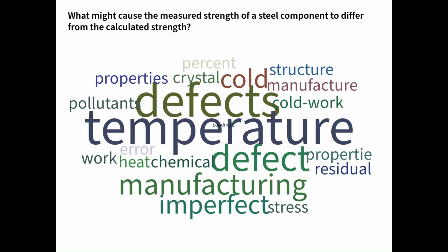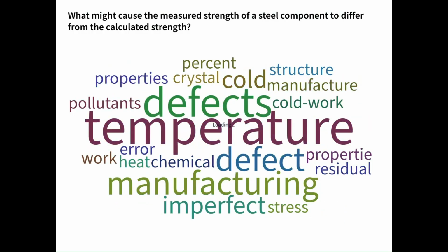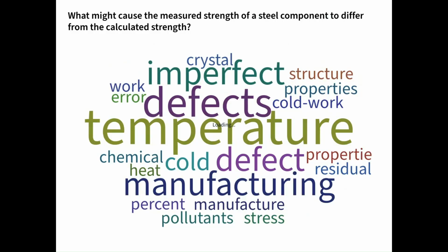You say, I'm going to roll a half-inch plate. You ask them to roll you a plate to exactly 12.7 millimeters, and they're going to do it. And then you take a pair of calipers, and it's actually 12.66 millimeters. You didn't roll it perfect, right? You can never roll it perfect. There's always going to be some variability in the geometry due to the way that the crystal structures work, the properties, some stuff with cold working.